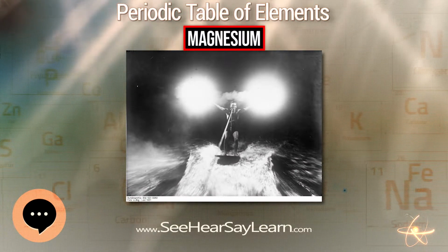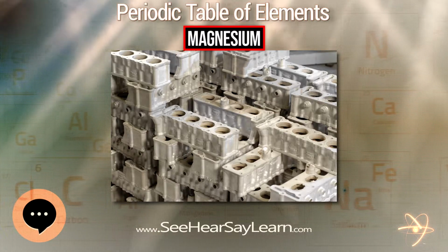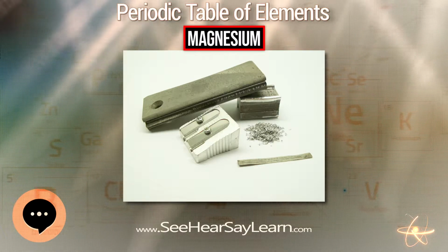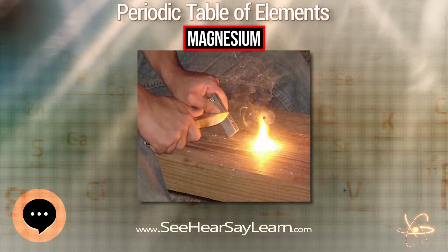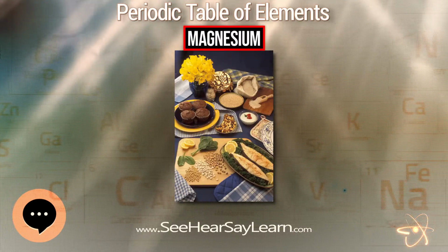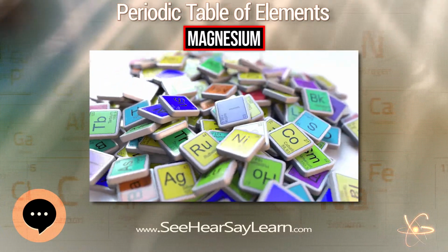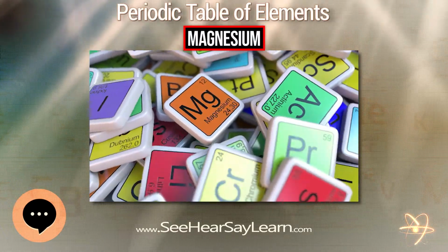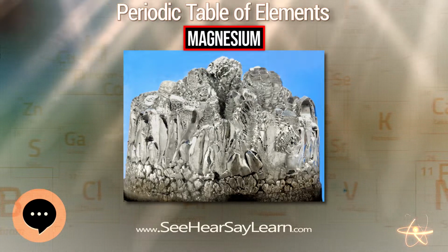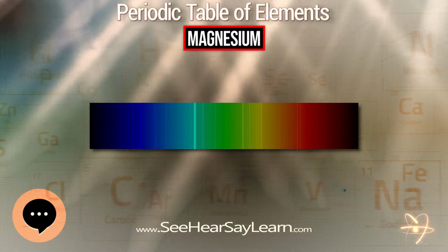The general strategy for such alloys is to form intermetallic precipitates at the grain boundaries, for example by adding misch metal or calcium. New alloy development and lower costs that make magnesium competitive with aluminium will increase the number of automotive applications. Because of low weight and good mechanical and electrical properties, magnesium is widely used for manufacturing of mobile phones, laptop and tablet computers, cameras, and other electronic components. Magnesium, being readily available and relatively non-toxic, has a variety of uses.